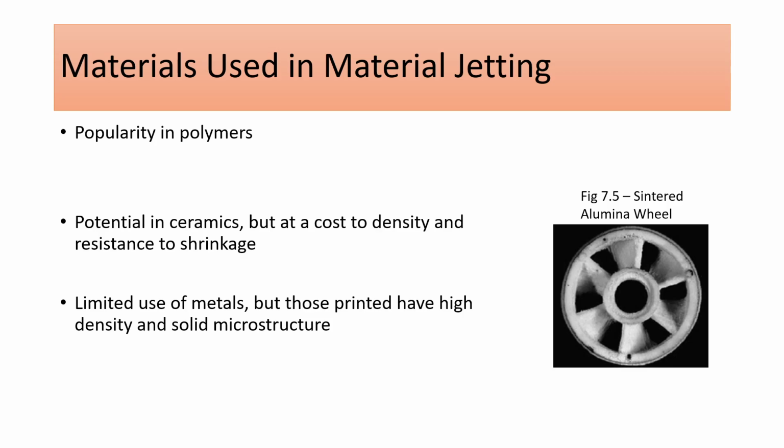Other than the fact that it is one of the only commercially available materials for material jetting, the popularity of polymers is likely due to its viscosity. Commonly, the maximum printable viscosity is around 20 to 40 centipoise, which is the equivalent unit to millipascal seconds. However, high viscosity liquids can negatively affect droplet formation and clog nozzles.